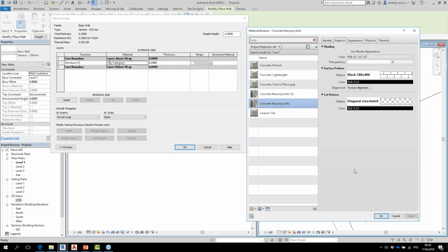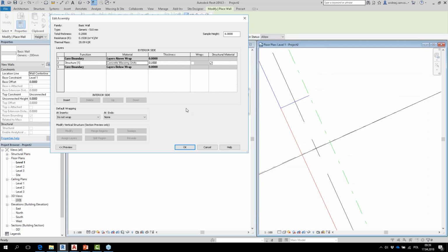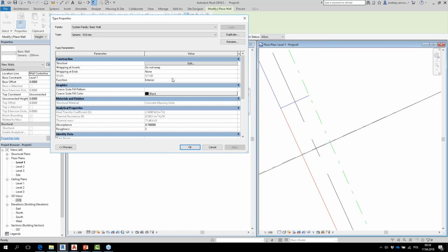Let's say that I want to approximate the material this building is already made of, okay? And of course I have to change here the thickness to 0.51 because of course the main units are meters. Okay, here this is just a name, I can put it like 51 centimeters. This is up to me how I'm gonna name my walls, okay?